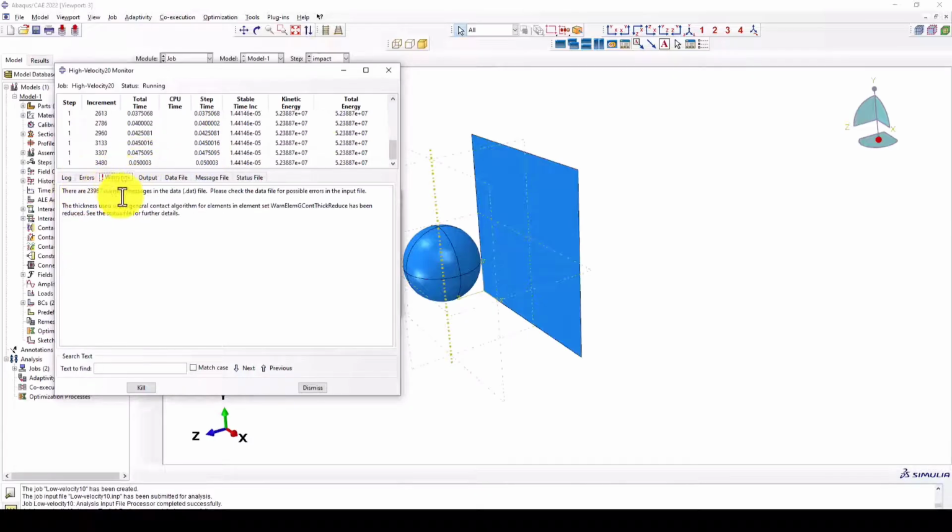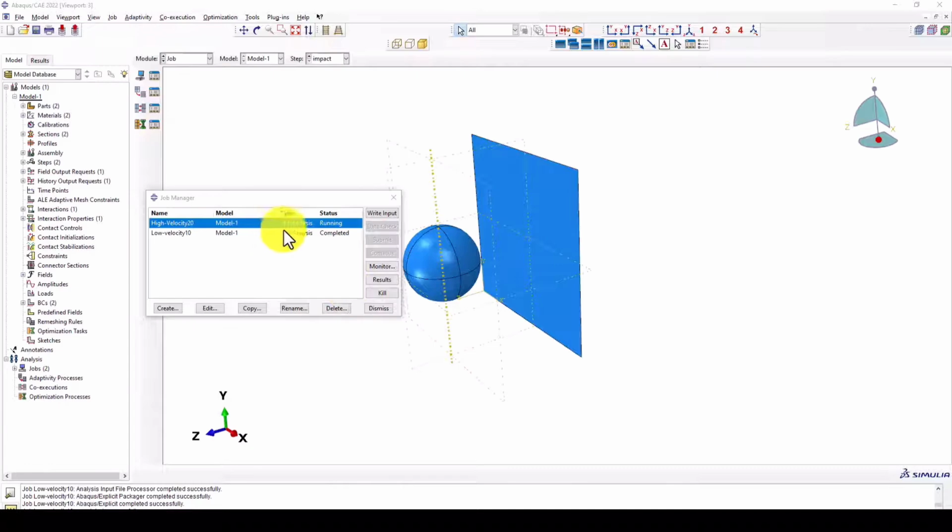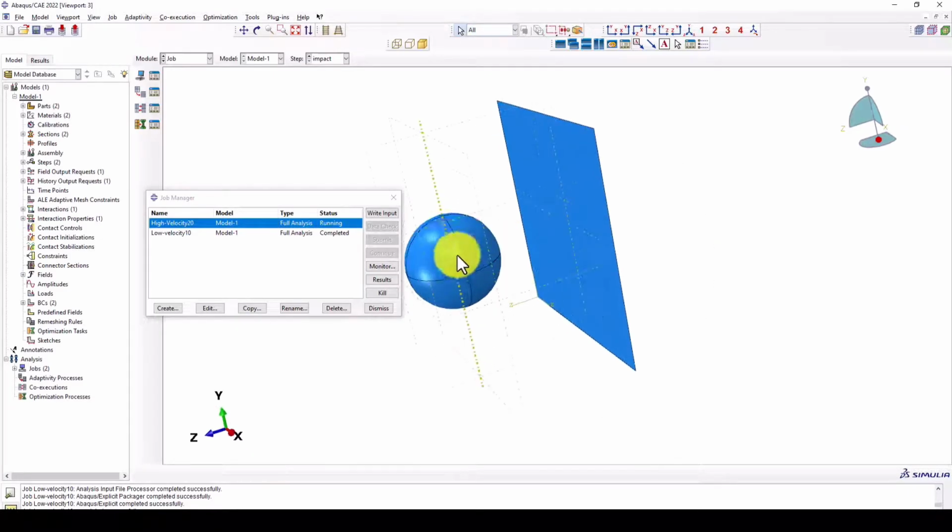The material we are considering is isotropic, because we know the difference between isotropic and anisotropic. The major one is in the behavior. Isotropic behaves the same in all the directions, and anisotropic varies in different directions. For example, isotropic is steel and aluminium, and anisotropic is composites. Isotropic is very easy to model, and it's a single set of properties. But anisotropic is also within the capabilities of Abaqus. We can also define anisotropic materials. We need to define the direction specific to the material data.